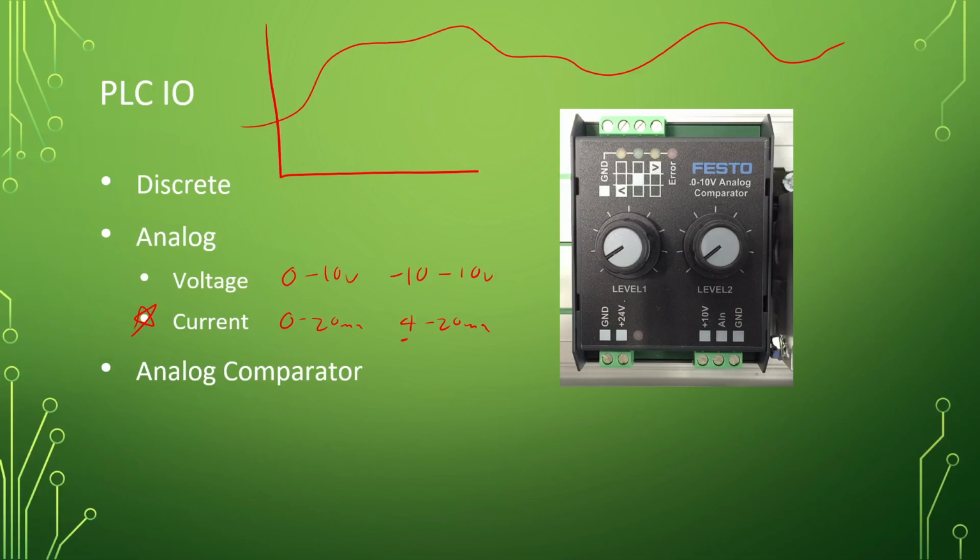Either of those is a possibility, so it is definitely something you need to be aware of. This is why, as far as I'm concerned, 4 to 20 milliamp is your best option. Yes, you lose range and useful accuracy, but it gains you known detection of your sensor.